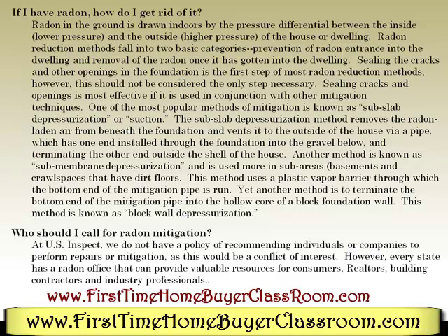Now, if you have radon, how do I get rid of it? Radon in the ground is drawn indoors by the pressure differential between the inside, which is the lower pressure, and the outside, which is the higher pressure, of the house or dwelling. Radon reduction methods fall into two basic categories: prevention of radon entrance into the dwelling and removal of the radon once it has gotten into the dwelling.